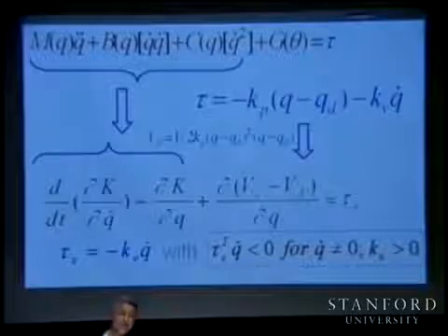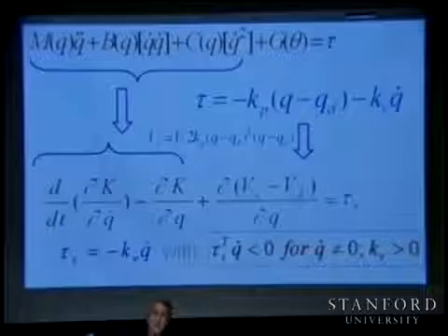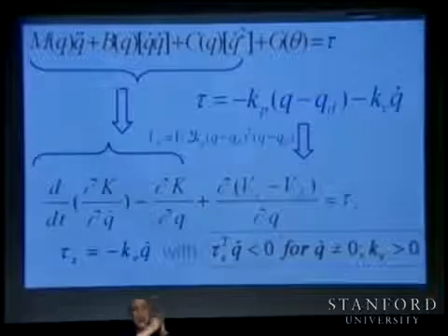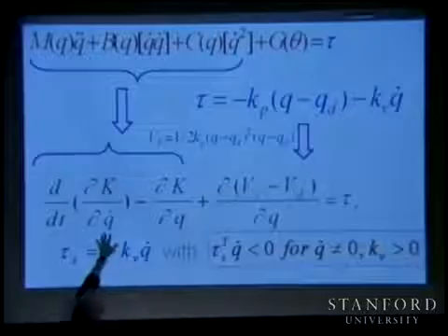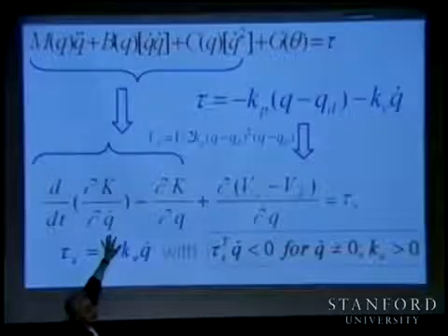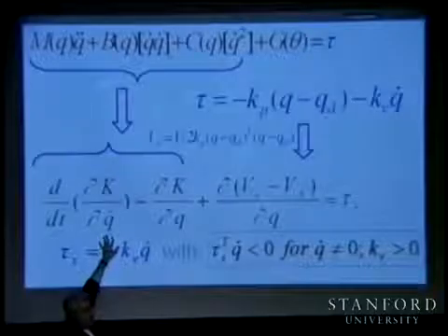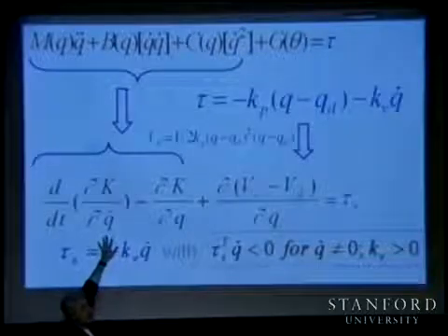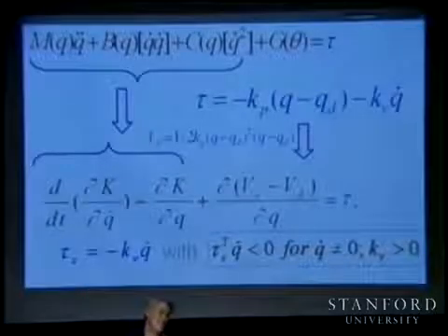But this doesn't tell you anything about the performance. It tells you, yes, you're going to move and reach that configuration, but along the motion you have all the coupling. Whatever coupling you have is going to appear in the kinetic energy derivatives, and that will produce the inertial forces. So if you're moving to a goal position, there is no problem.